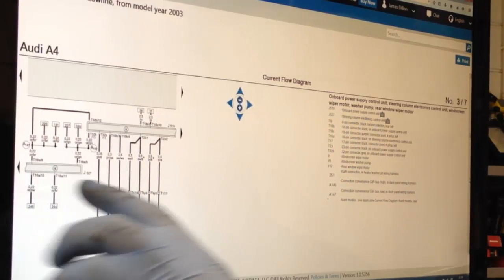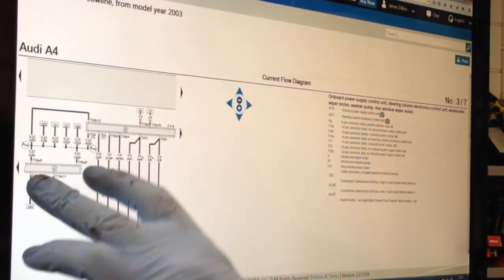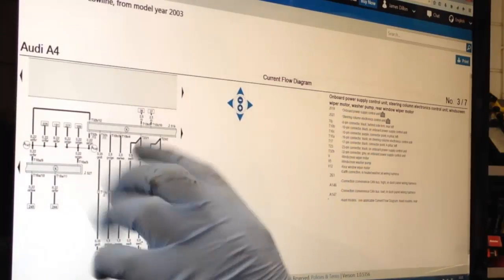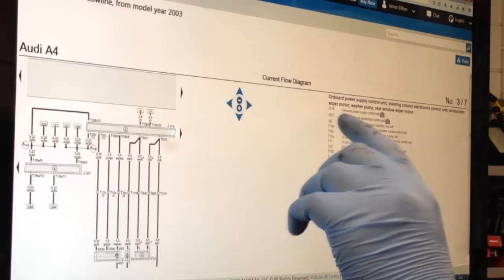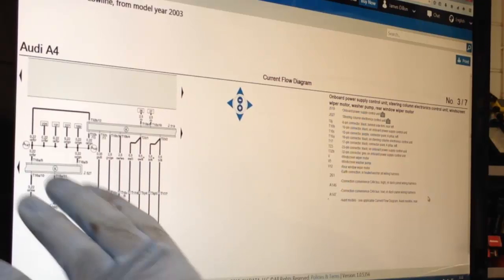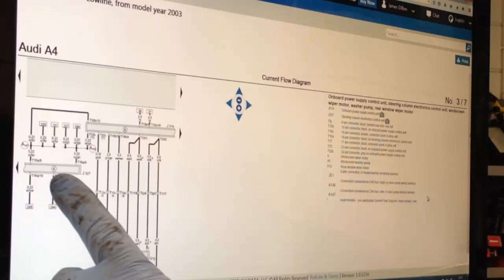We can see then, looks like the end of the control module there, and it's linking by these two wires by the look of it into two splices, and then these wires go to another unit, 509, onboard power supply. So steering column, which is where we're going to zone in, is connected to the onboard power supply. And actually what is very interesting, we can see the distributed function here. Connected to this unit on the previous page are my wiper stalk.